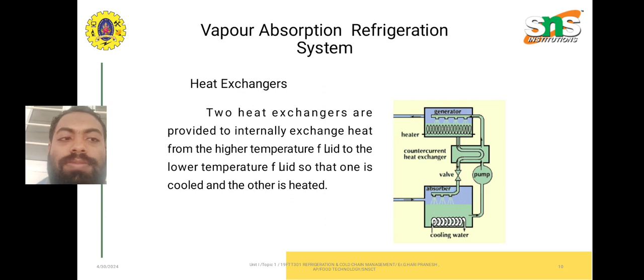Heat exchangers. Two heat exchangers are provided to internally exchange heat from a higher temperature fluid to a lower temperature fluid so that one is cooled and another is heated. Here you can see two heat exchangers, between the generator and the absorber, and the solution passes through a heat exchanger.